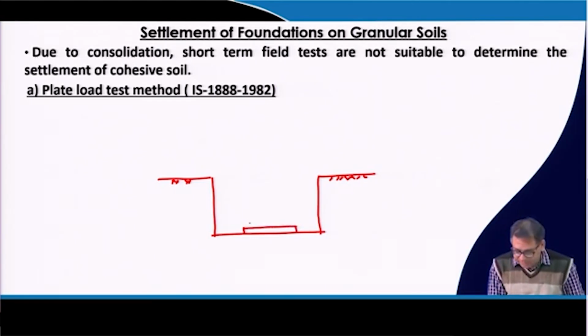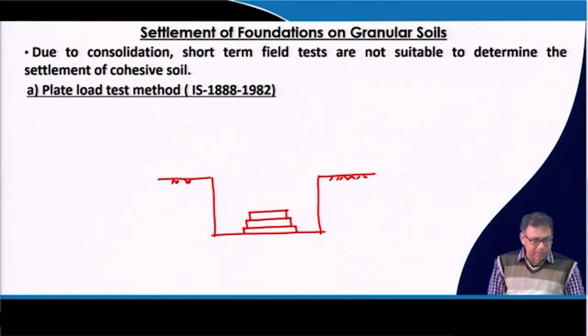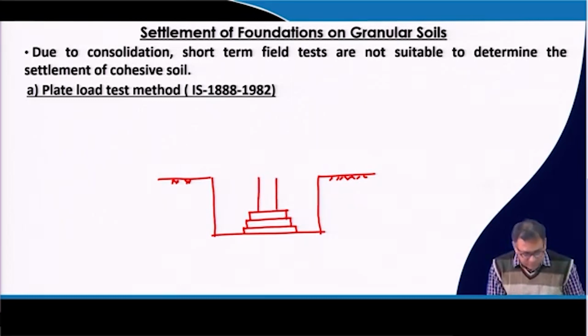Then we will place this stack plate, because these will help us to give the load on the plate. So, this is your hydraulic jack, and through this hydraulic jack we will apply the pressure, and we will use the reaction frame also.